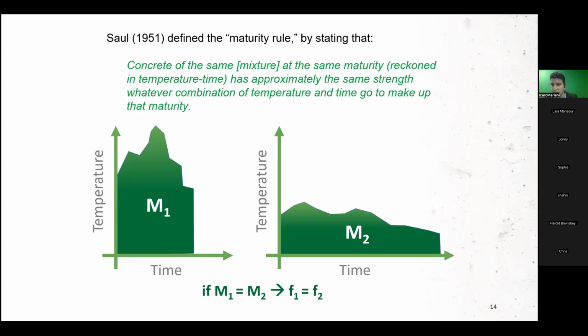The biggest advantage here is that on your left-hand side, your structure on site is generating a peak temperature because it has a mass effect, compared to a cylinder that has this process spaced out. What happens is that you gain strength much more rapidly at the job site compared to a sample that is being cured at lab conditions. That's why you can move faster installing sensors on site.